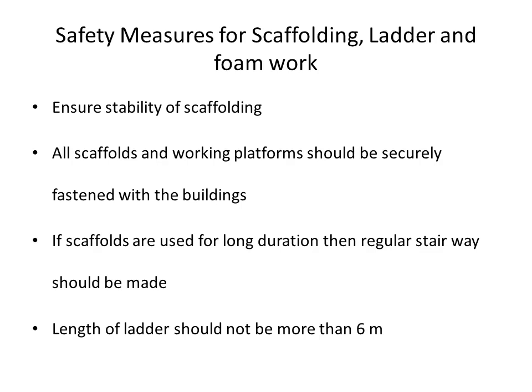And the next one is, if scaffolds are used for a long duration, then a regular stairway should be made. That is, if the scaffolding is going to be used for a longer duration and a lot of workers are going to use it, then it should be made like a regular stairway, with a width so that two people can pass the stairway at the same time.